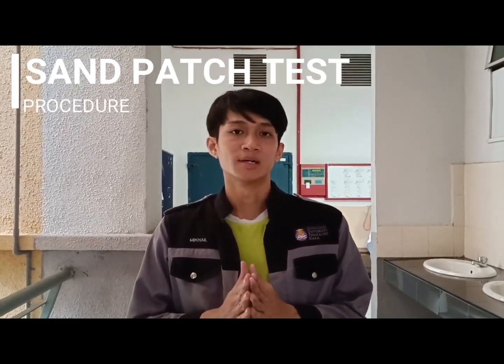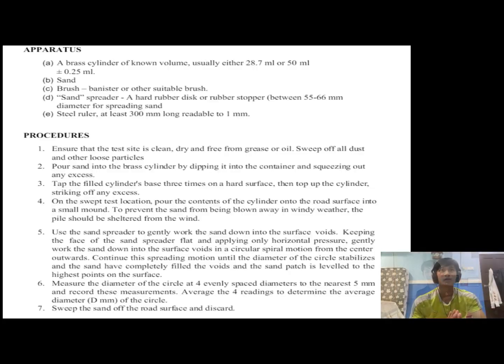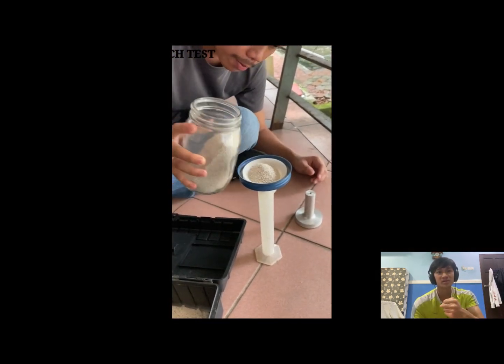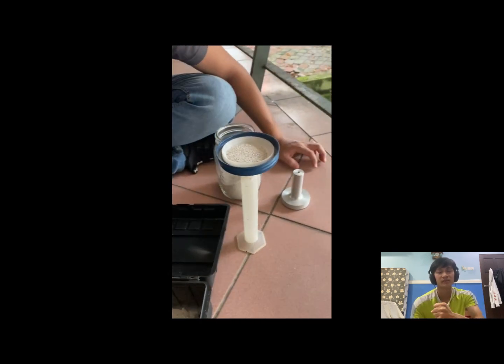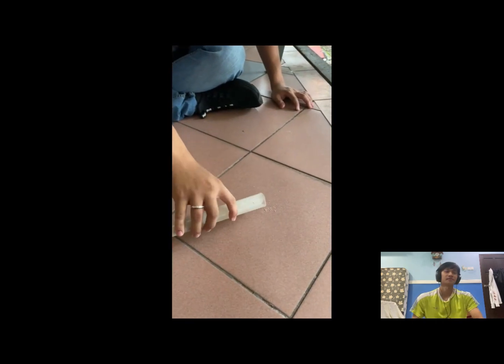Okay, now we are going to conduct a sand patch test on different types of surface: smooth, medium and rough. So let's start. For the sand patch test procedure, first we have to pick a surface, and once we have chosen the first surface, we have to clean any debris on the surface to make sure there is no obstacle, because we are going to put sand and make a circular motion to spread the sand, so we don't want any debris to disturb the sand while we are spreading it on the surface.